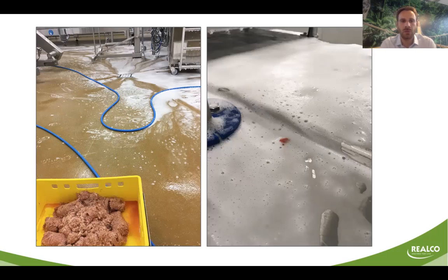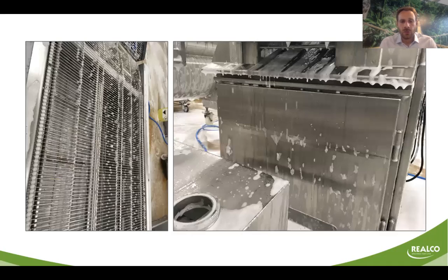So it's really important to follow the operators, because you have designed a cleaning protocol, but you need to be sure that the people are really handling the cleaning and the sanitation, following the rules and applying the product very well. I told you also about the concentration, so it is also important to validate that the foaming units or dilution units are in fact diluting the product at the right concentration, because if it's not the case, you will not get sufficient concentration, and it can impact, for example, the quality of the foam.